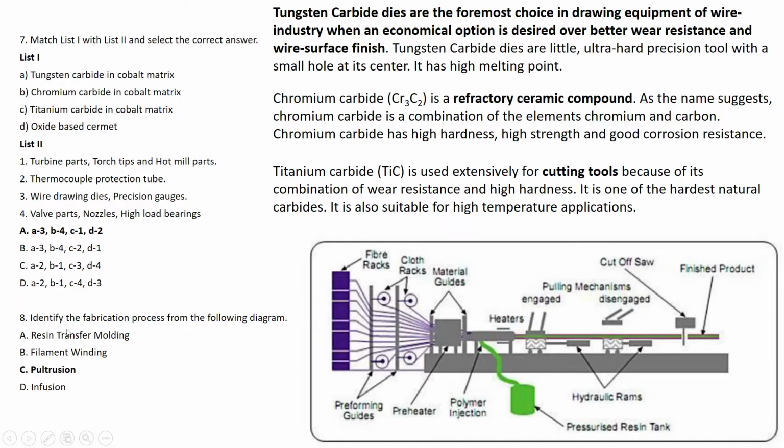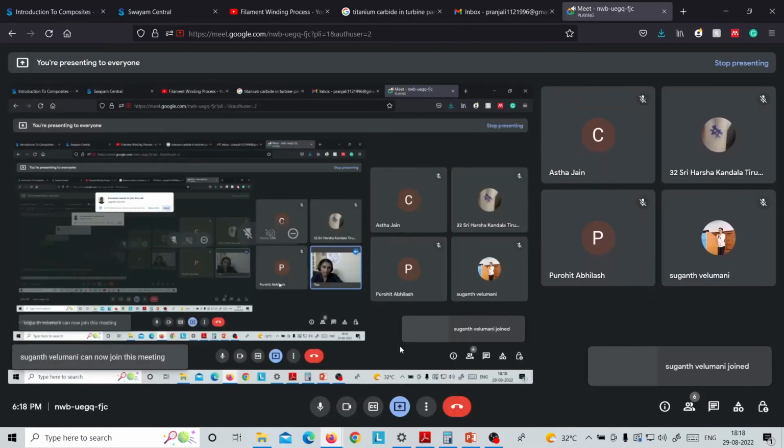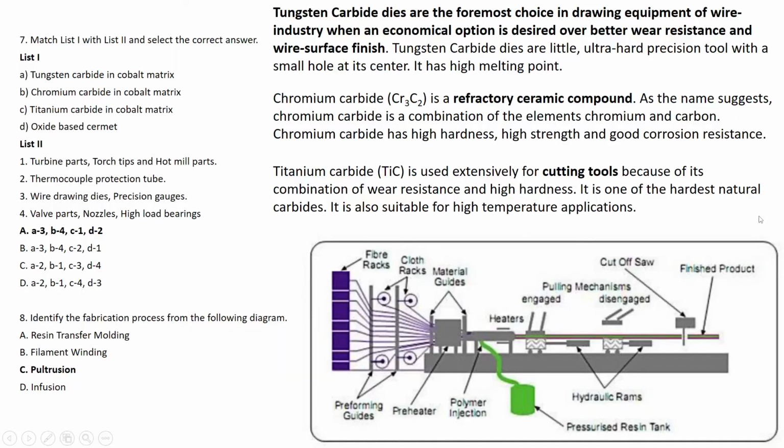Then the fourth one was which is this fabrication process. Out of all these, pultrusion was the only automated process, and this schematic itself shows that it comprises a completely automatized process. We can see the fibers start from here. They heat, then resin is also placed inside. Then they heat simultaneously. It's being pulled out, and after curing, it's cut at the same time. So we can see that within a single process we are able to obtain the finished product all in an automatic way.